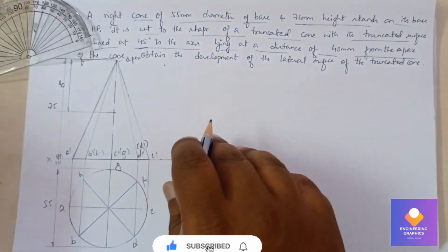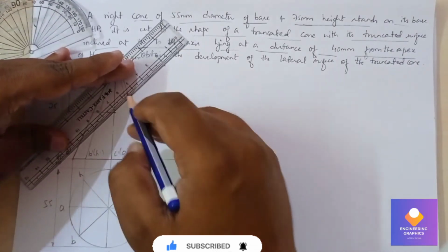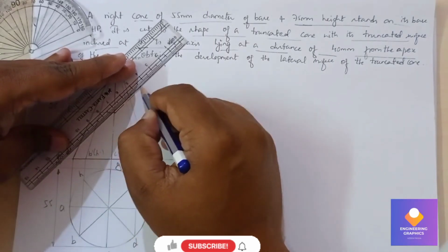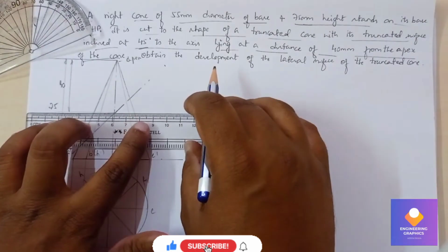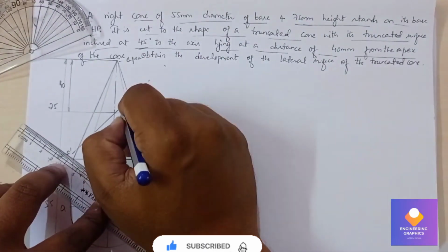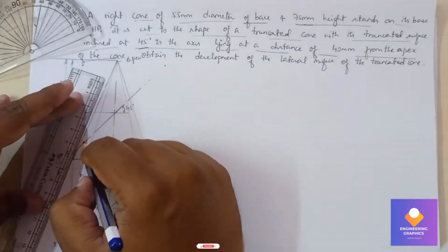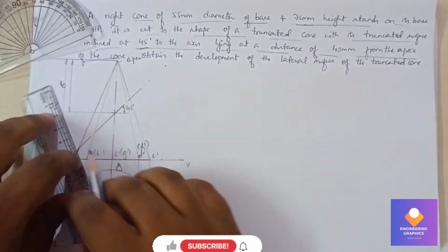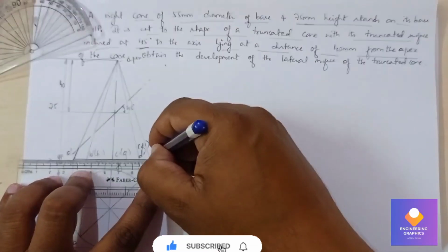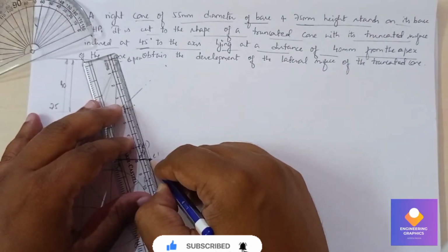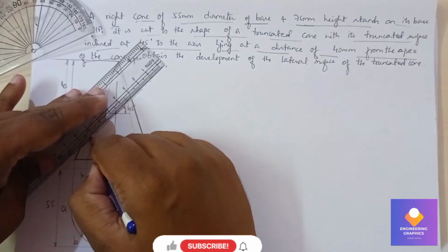Okay, now draw a line, the section plane, passing through this angle point, so cutting all these edges, all these generators, you can say. Now you can show the angle. After showing the angle, you can dark the cut portion. You can dark this cut retained portion.